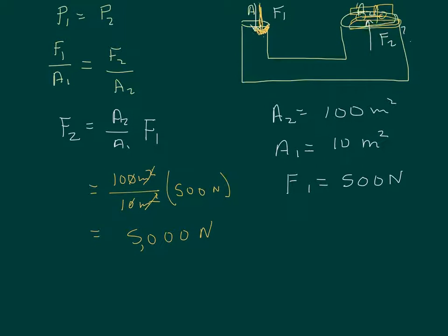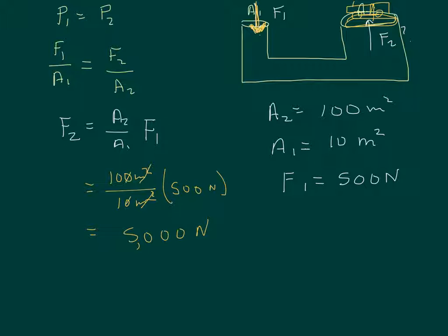And this is the principle behind all hydraulic systems, that they allow a small force to lift a very large force at the other end. Or likewise, we might want to push on F2 with a big force and we would move the fluid in here a much longer distance.